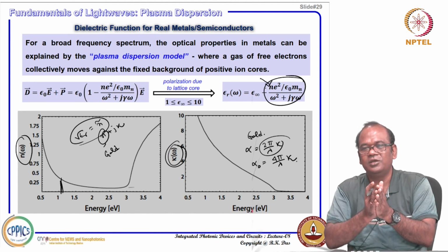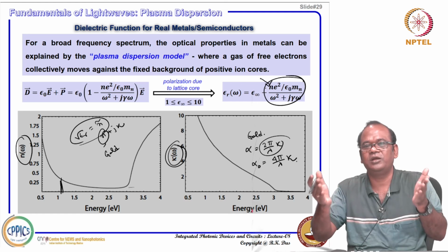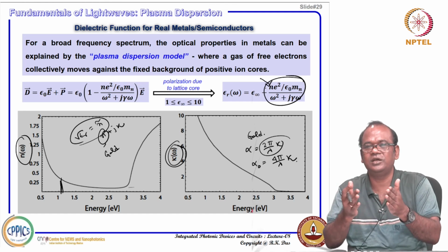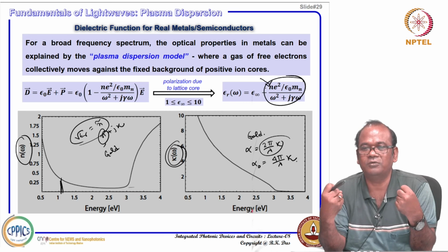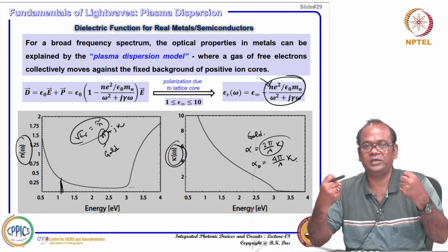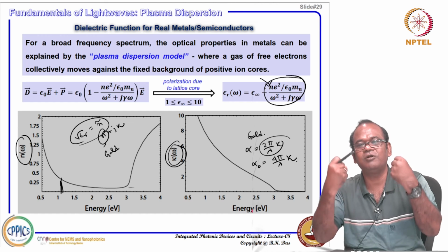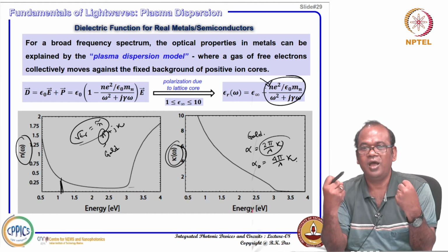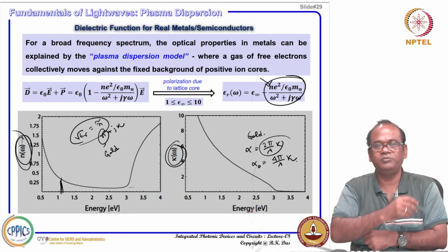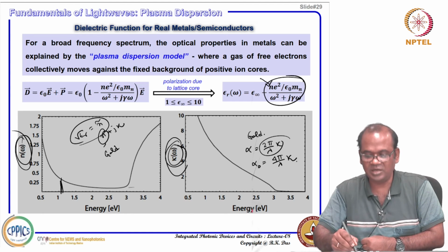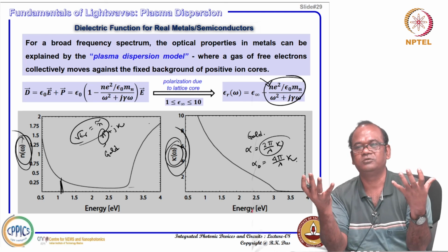In a semiconductor, you can have some kind of diode junction, and in the junction region you can control the carrier concentration by bias control. If you give an electrical bias, you can control the carrier concentration, and then both the real part and imaginary part of the refractive index can be changed.